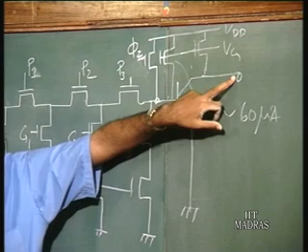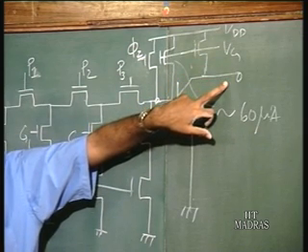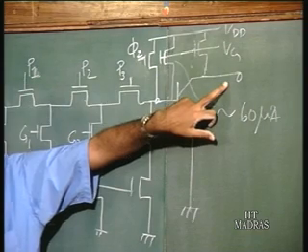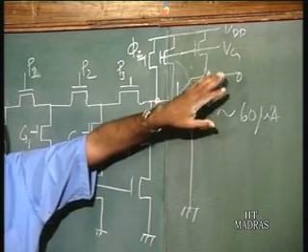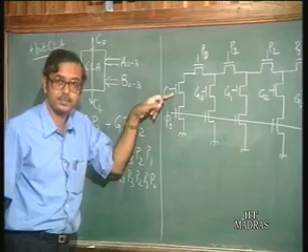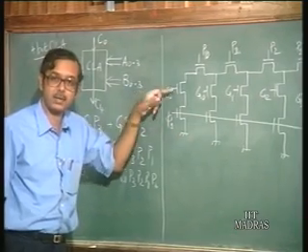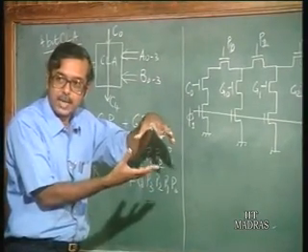If VDD is 5 volts, the output voltage will go all the way from 0 to 5 volts. I mean not exactly 0, but close to 0 to 5 volts. So, this output voltage has a full swing. So, this output can drive the input of the next stage, that is, if you have the series of these inverters, of this 4-bit carry look ahead adders.